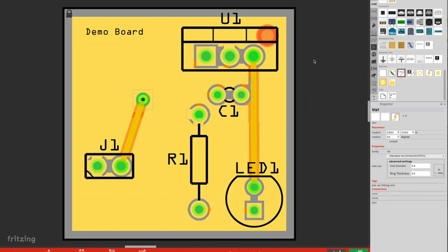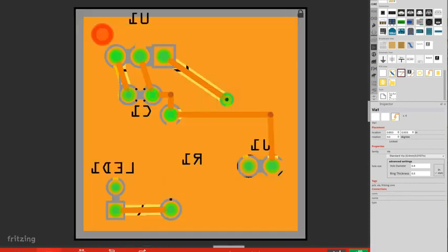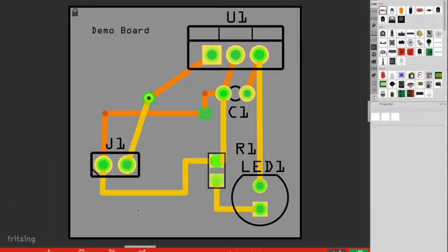There you are. Essentially what it's done is it's filled both the top layer and the bottom layer with copper to join all the grounds together. So it's well grounded, very free from interference, a good thing to do on the whole. Okay, so I think that concludes this particular stage of the demo. I'd just like to run through a couple of other examples just to show you some of the other things that can occur.